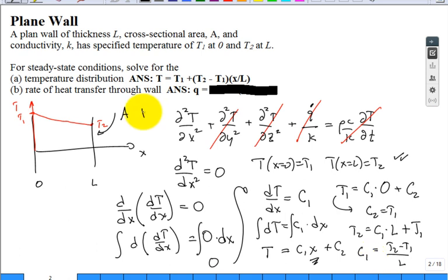This was the heat equation or the heat diffusion equation. Our other commonly used equation is called Fourier's law. What's Fourier's law? Fourier's law says that Q is equal to minus KA dT/dx. True or false? Yeah, we like that. We already have an analytic solution for it. So you take that analytic solution for the temperature distribution and you evaluate dT/dx. What do you get for dT/dx?